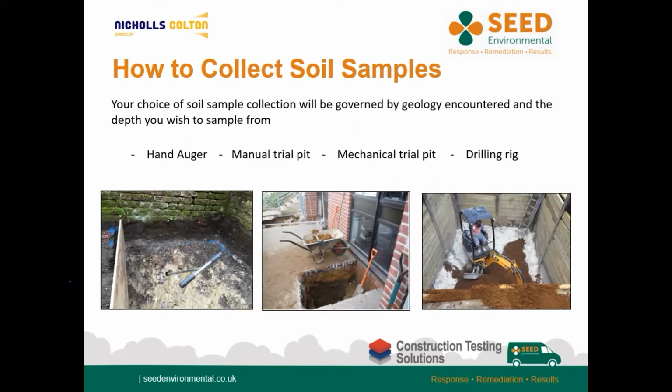The British Standard 10176/2020, as mentioned earlier, states that sampling devices used for collection of samples should be made of materials that do not react with, absorb, or otherwise interact with the sample, and shall be able to withstand the forces applied during the taking of the sample without being so damaged as to compromise their proper function. Non-disposable devices shall be capable of being physically cleaned and decontaminated. It is important to be able to undertake this decontamination exercise between sample locations.